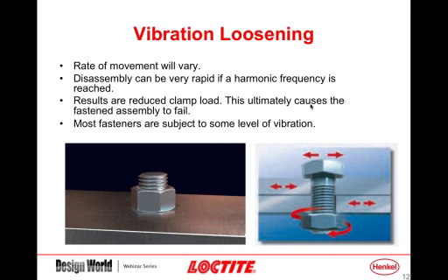All right, so vibration loosening. Don't need to say an awful lot on this particular slide because I think most everybody's pretty familiar with the fact that when you get either thermal transitions, which cause expansion and contraction of fasteners, or, as you can see on the right-hand side, any type of vibratory loads, you can get a shifting between the nut and the fastener. And as soon as you get any type of micro movement caused by thermal or vibration, that's when you can get a loosening on this fastener, and that will reduce your clamp load and can result in failure.